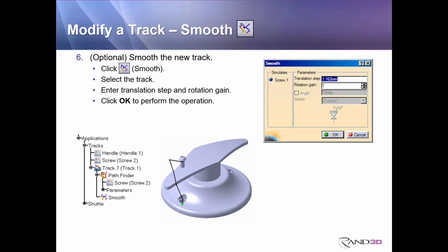And here's the downside to smoothing a path: by smoothing the path, sometimes it will actually reintroduce a clash condition. So this is on you guys. You should always do your due diligence and play the track and make sure that you don't have any clash, and you can easily do that with the clash detection that you have on.